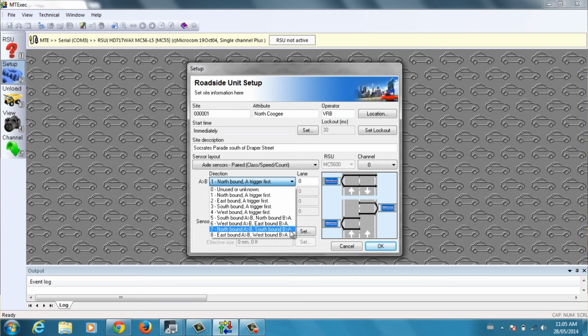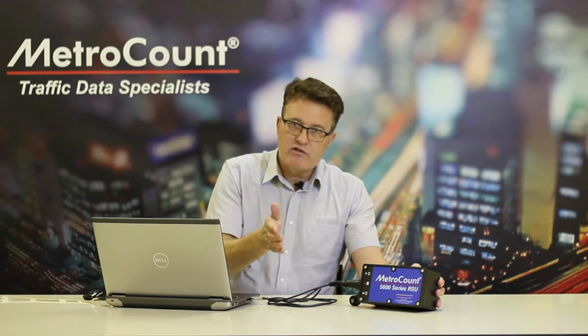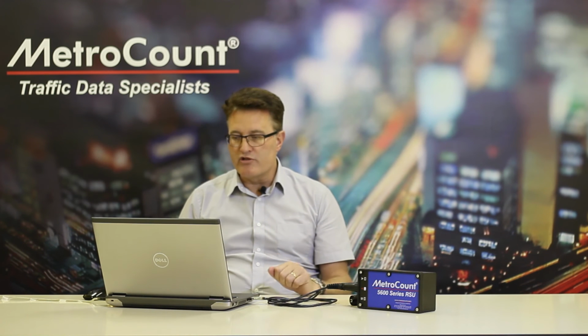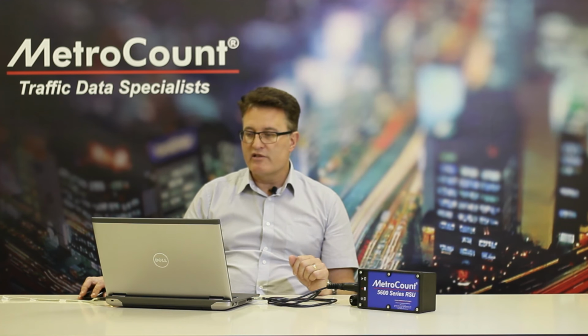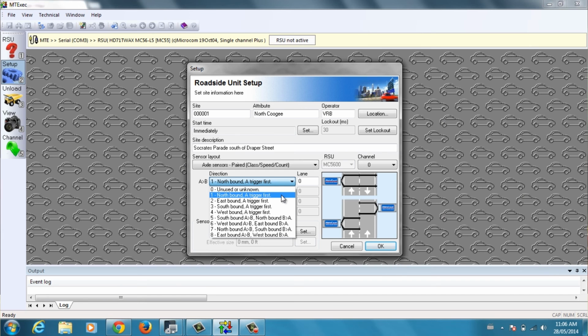The logger is clearly marked with A and B sensors, and depending which tube you plug into the logger, that defines the direction of flow over the tubes. In the particular example that we did, the southernmost tube was the A tube, the northernmost tube was the B. So northbound A to B, southbound B to A. If we flip the hoses around, we might be southbound A to B, northbound B to A, but in this case, direction code 7. Note the unidirectional options here. Quite often you conduct a survey with just a single lane and you would choose direction codes 1 through 4, but this is bidirectional, so direction code 7.